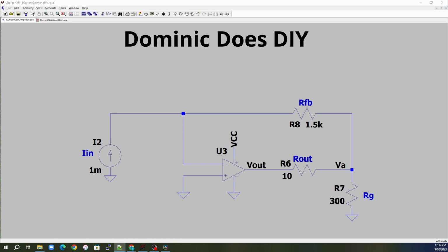So now part 2, we have to determine what the reason was behind it failing. Well, the reason was these negative voltage levels. Because of that, the op-amp couldn't compensate correctly, and so the formulas weren't working. And then part 3 was to correct the circuit in a way to allow it to function as expected. So how can we make this circuit work?